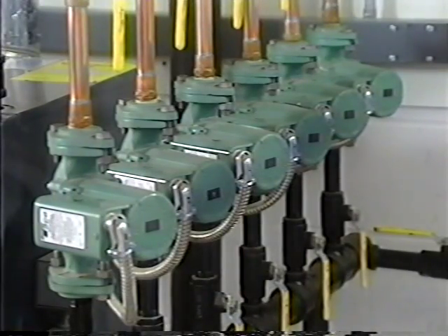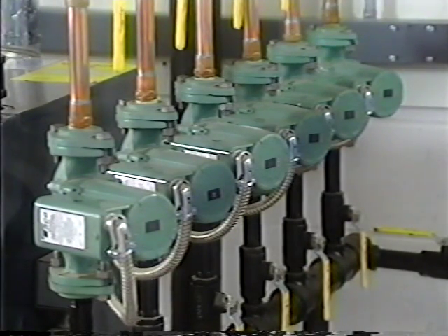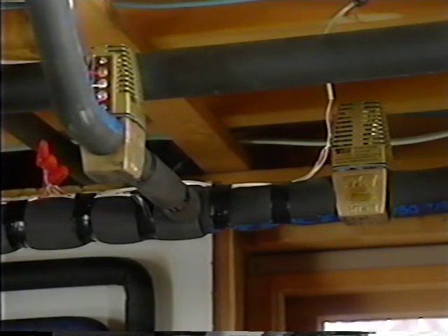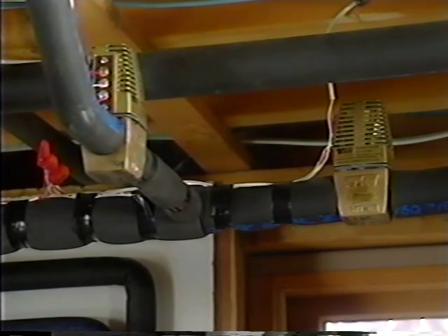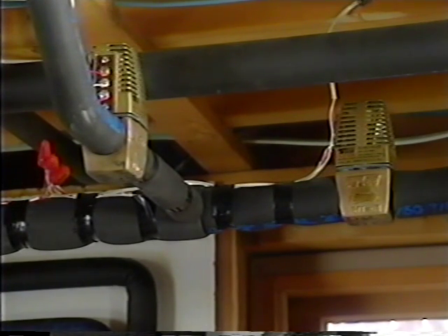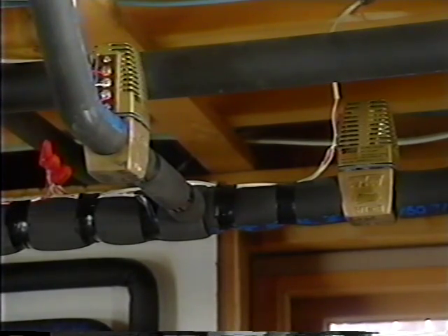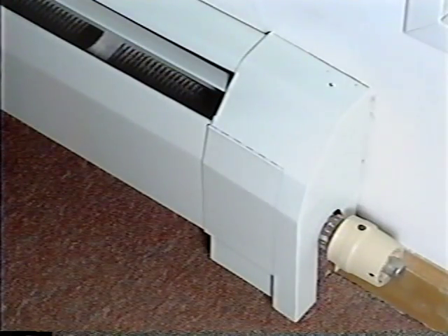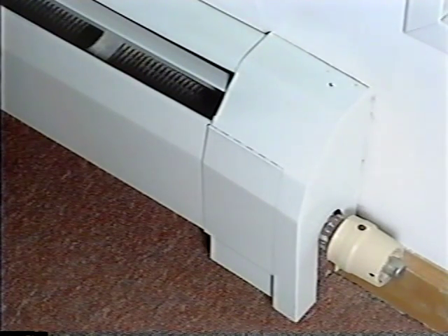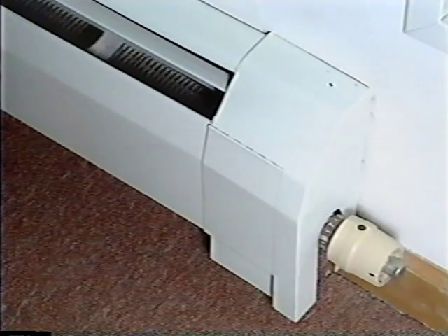There are three basic methods used to zone hydronic systems. Circulators can be installed on each zone, and when there is a call for heat, the zone circulator moves water through the zone. A zone system can also incorporate electric zone valves. These valves are electrically controlled globe valves that open and close based upon a call for heat from the thermostat. The third method uses non-electric zone valves, which can be installed at each piece of baseboard or radiator. Each one of these methods of zoning will be discussed in more detail in later sections.